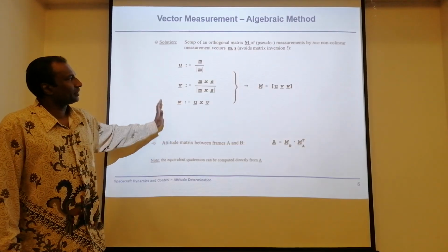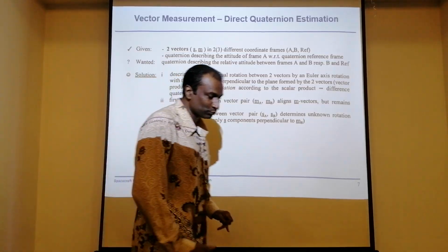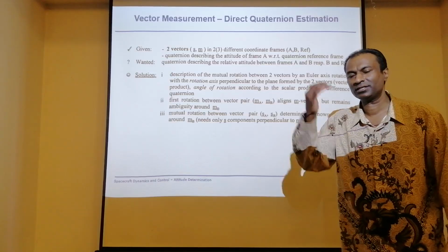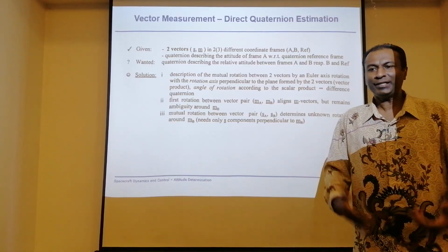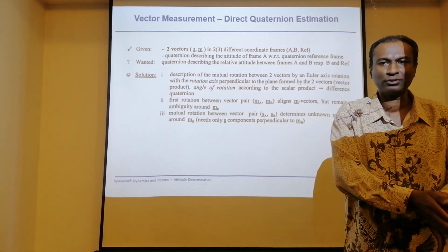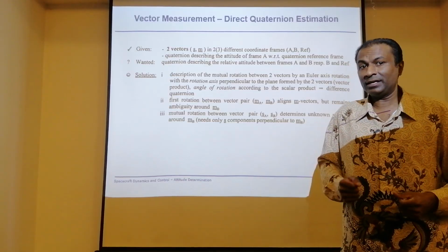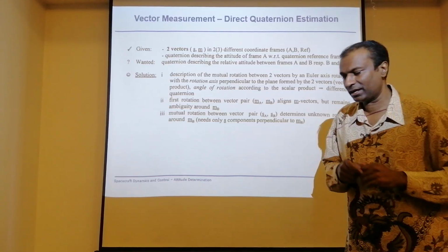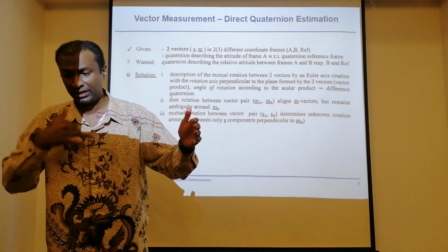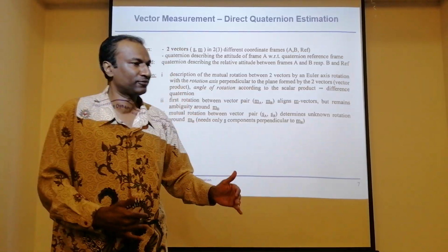Okay. Now, go on. We have also given you quaternions. Attitude information, the initial quaternion, is given as an attitude input. Then we ask you to express this in local vertical, local horizontal, or express this in body coordinate. We have also done that. The deviation quaternion that we always talk about is the body coordinate with respect to local vertical, local horizontal. That is the deviation quaternion that we've always been finding.